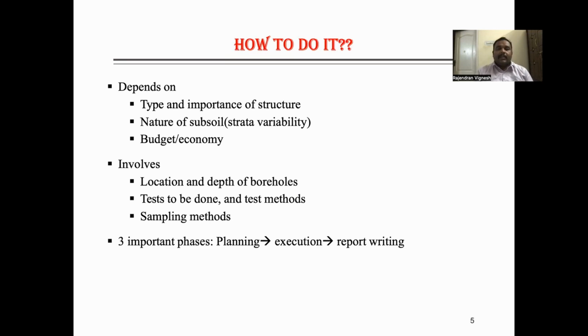Basically, there are three important phases in soil investigation. First, we need to plan out the possible methods, identifying just through a walkthrough survey, and then through a detailed methodology, that is the advanced methodology. Then execute the different types of tests in both basic methods and advanced methods, write the critical points about the site investigation, and then go for the report writing.